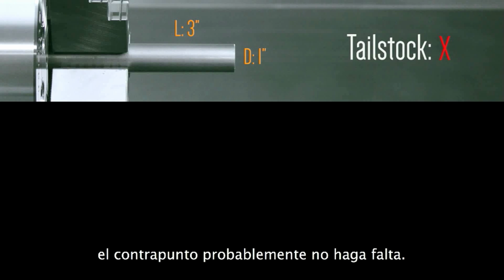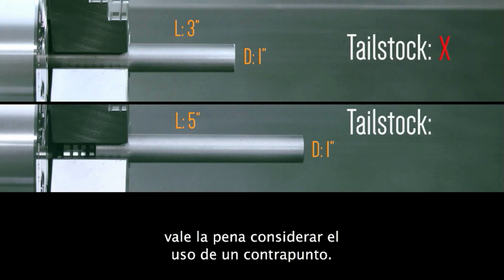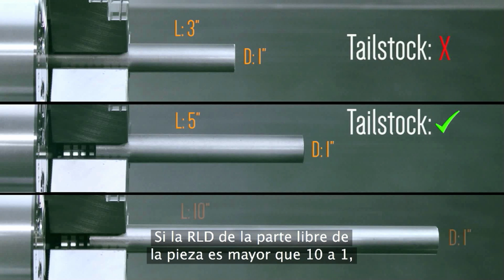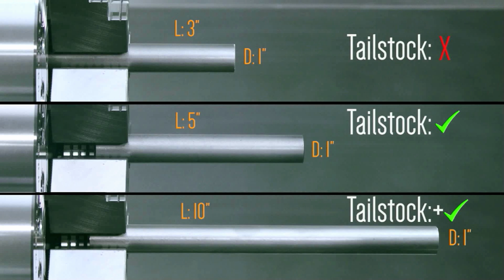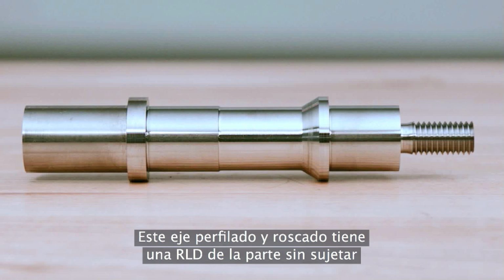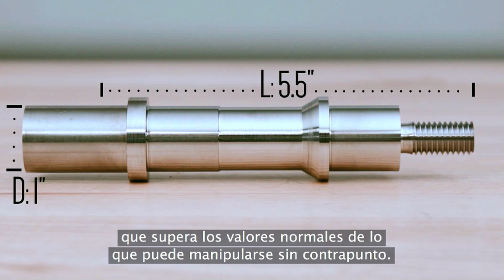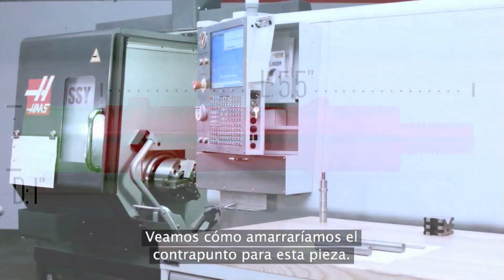So, to summarize, we recommend, when unsupported L to D equals 3:1 or less, tailstock support is probably not needed. When a part's unsupported L to D ratio is above 3:1, now it's time to start considering tailstock support. And when unsupported L to D is over 10:1, we'll definitely need tailstock support and maybe something more, like a steady rest. This profiled and threaded shaft has an unsupported L to D that's beyond what is typically possible without a tailstock. Let's look at how you'd set up your tailstock for this part.